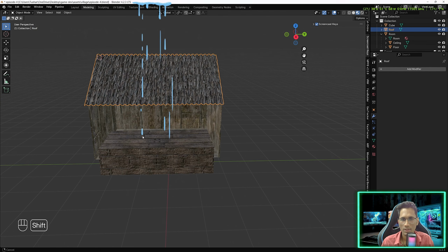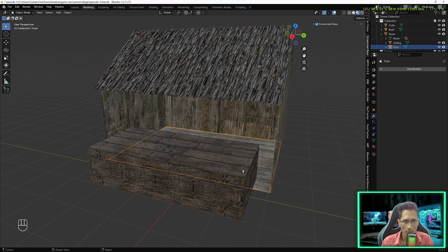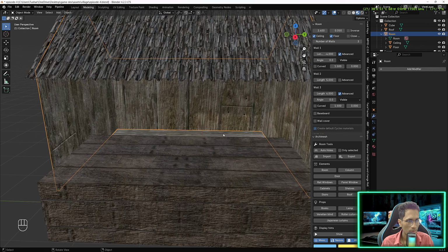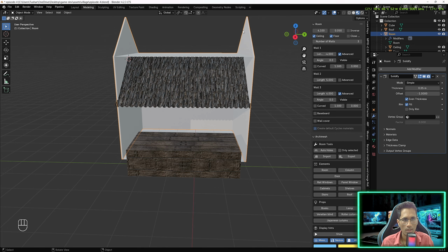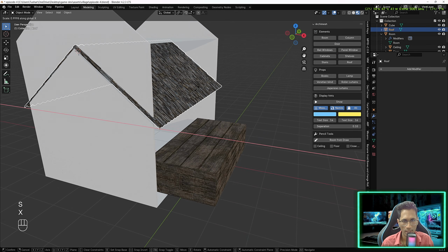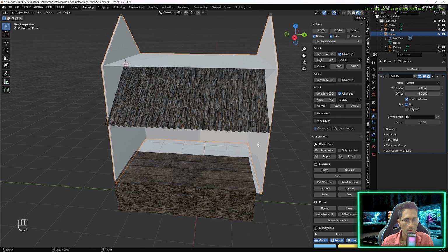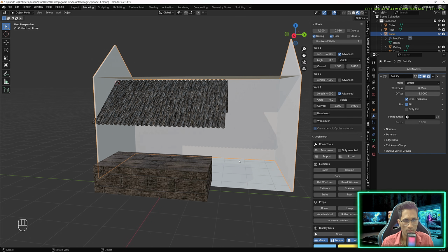So for this, we have to increase the area of the room and this roof. And we also have less space on the left and right and in the back. So we need more space. So what I'll do, I'll select this room. I'll go to create, that is our Archimesh. And here I'll increase the size by 4.1 in top, so that you can extend this roof like this. Okay. So after this, I also want an area in terms of width. So the second wall that is behind, I'll increase its length by 7.5 just to get some more area.